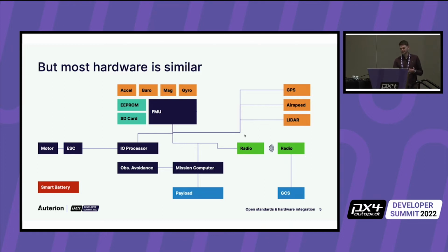You would have external sensors, so sensors that you can't really put in your avionics bay and that you would need to put on the external of the frame because they need airflow, like airspeed, so you need air coming in. So you would have an airspeed sensor that you connect with a cable. You have a GPS sensor, LiDAR distance sensor. You'd have motors connected to ESCs.